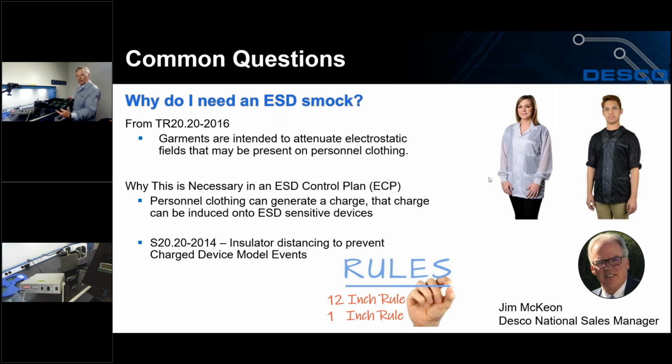So this is a very common tray that you load up with circuit boards, or it might be an open tote box, or anything where the product isn't already shielded. If I were to pick this up and walk across the room, which is very common, holding a tote box, and I wasn't wearing my smock, I might induce the charges onto my circuit board. Consequently, if I was sitting at my workstation like I was before in my chair, and I slide into my workstation and I start soldering, or I'm looking under my microscope, I can also induce those charges from my clothing.